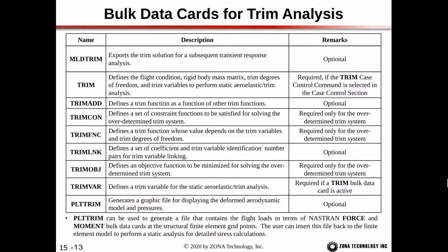Finally, the plot trim can be used to generate a file that contains the flight loads in terms of the Nastran force and moment cards at the structural finite element grid points. So the user can insert this file back to the finite element model to perform a static analysis for detailed stress calculations at the trim condition.